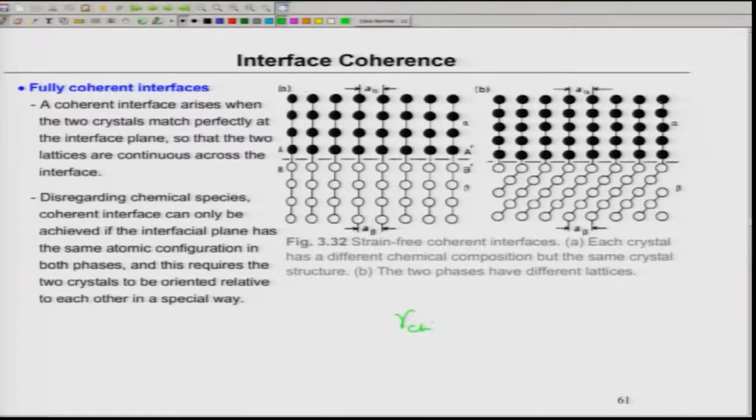They have to be related in a very special way, otherwise this kind of situation will not occur. You know, in a copper silicon system such a thing happens. The silicon rich phase, which is called kappa, has a hexagonal crystal structure. On the other hand, the copper silicon phase has an FCC crystal structure. Whenever the kappa phase, which is silicon rich, forms within this copper silicon FCC phase, the interfaces are arranged in such a way that the 111 plane of FCC copper silicon will be parallel to the 0001 plane of the HCP kappa phase.